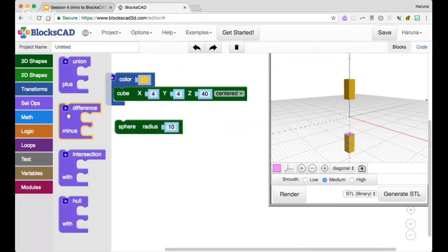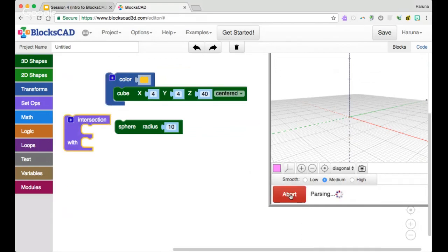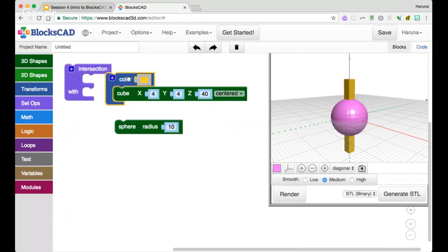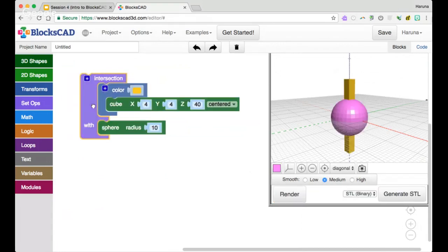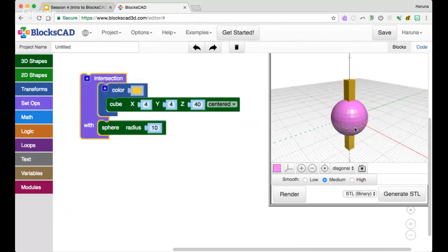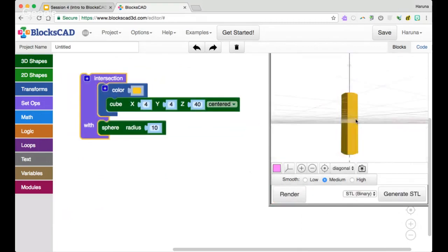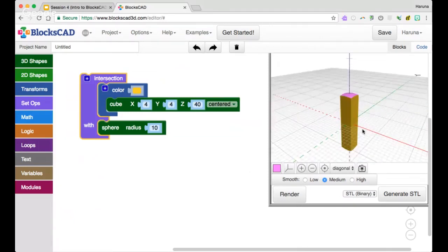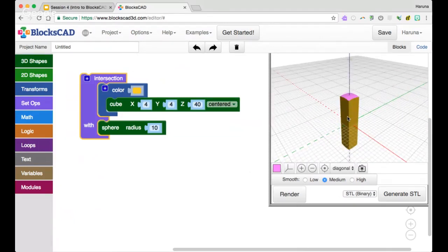And this is really helpful because in Tinkercad you've seen the whole and the object, but in this case you are really planning what your end object is going to be, and that goes into your plan. Hence, the order of operation matters, how you plan the object matters, and so on and so forth. So intersection will take the part that both geometries occupy. So in this case, you will get this portion, which was taken up both by the bar and the sphere.